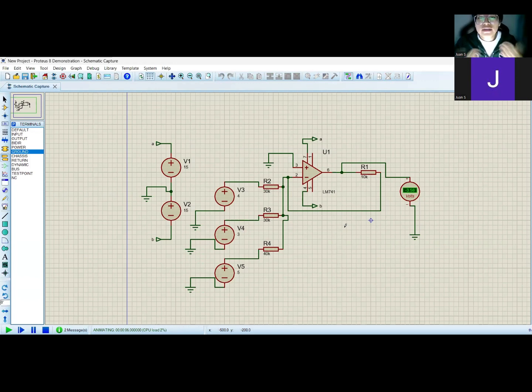Remember polarity, maximum values, and overall check everything that you can do in this program. For example, let's replace this by 10, 20, and let's say 30. You would say, oh my God, it's going to give a big number. However, it's just limited to minus 13.9, mainly because of the voltage that's been provided here. So keep that in mind, because it can't go over 15 or minus 15. It could multiply by, let's say, 1,000, but it wouldn't work. So keep that in mind.